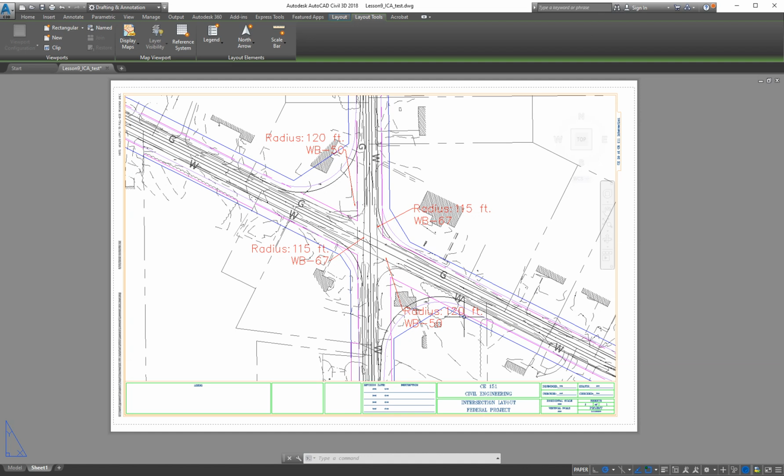Now, occasionally I have a layer that I turn off when I print, and it's just for me in design, and I'll put my own notes and sometimes my own dimensions in model space, but no one else sees that. That's what they call a scratch layer. I just use my scratch layer so that as I'm designing a road or something, I can leave myself notes in the drawing. And then later when we do sheets, no one else sees that. You can set in your layer properties a layer that's a non-print layer. I can see it, but it'll never show up on a plan sheet, luckily.